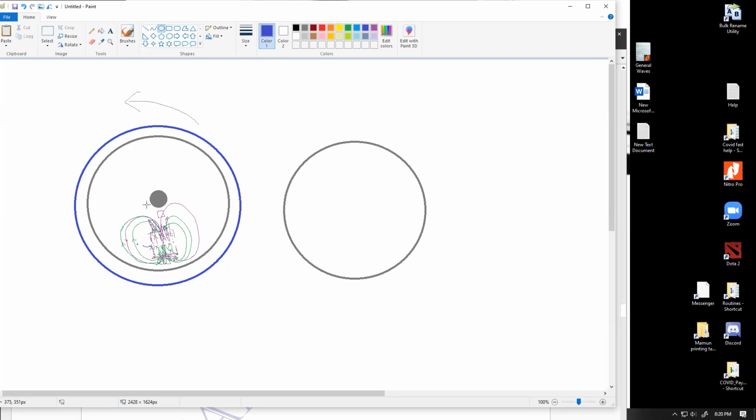So you'll have a high positive voltage at the center and a high negative charge at the periphery, which can work sort of like a DC supply, but it is not going to work as eddy current. But because you don't have any unaffected return path available, electrons cannot produce the eddy current within the metal disk itself. To have the eddy current available, you need alternate segments of regions which are affected by the magnetic field and non-affected regions. You need both of them. Yes, sir. Beautiful. Shubhro, go ahead.